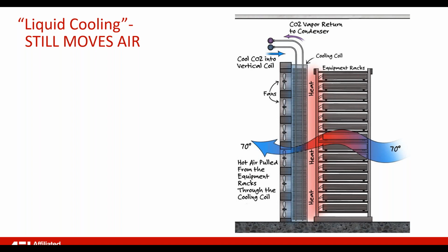But the thing about this is we're all still moving air. Every one of these scenarios, as shown, is still moving air across a heat sink internal to the IT equipment, which raises the question: when do we reach a density that we can't do that? And if we start increasing that supply air, instead of maybe 70 degrees F in this example, it increases to 80 or 90 degrees, depending upon a person's comfort with the recommendations from ASHRAE. All right, next slide.